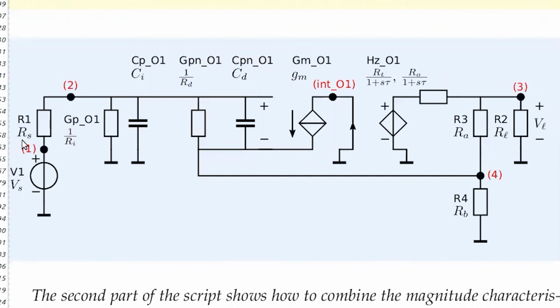And the pole of this input attenuator, if the controller for the rest behaves as a nuller, so if there is a huge loop gain, I would say, is like there is no current flowing in here, then in that case, it means that we just have a pole at the parallel connection of Rs and Ri and the input capacitance, exactly as we could see from the results given by the symbolic analysis.